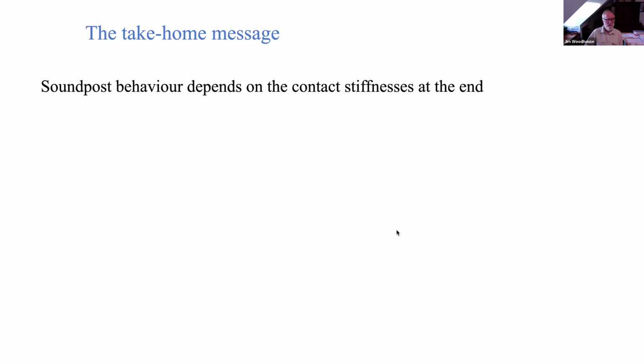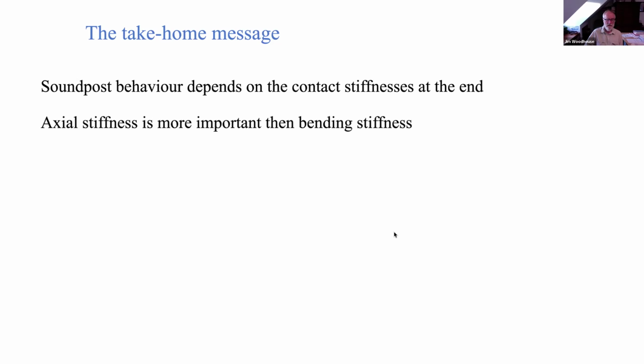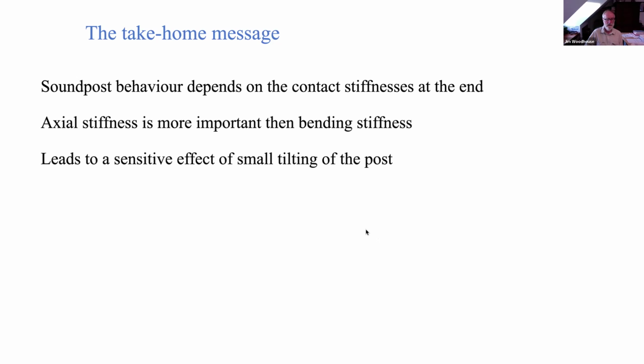The most important thing, perhaps because maybe you've never thought about this before, is that the behavior of the soundpost depends on these contact stiffnesses at the ends, which depends on how accurate your fit is, but also what the surface finish of the plates and of the ends of the post are. The axial stiffness seems to be way more important than the bending stiffness. That's good. That gives us a useful simplification.